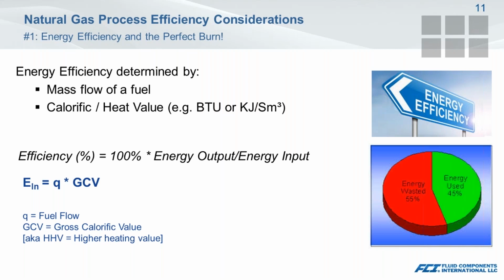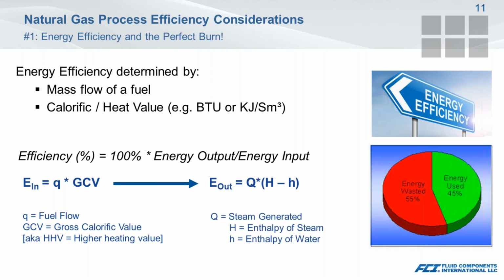One definition is to subtract the heat of vaporization of the water from the higher heating value. This treats any H2O formed as our output as a vapor. The energy required to vaporize the water, therefore, is not released as heat. LHV calculations assume that the water component of a combustion process is in vapor state at the end of combustion, as opposed to the higher heating value, which assumes that all of the water in a combustion process is in a liquid state.